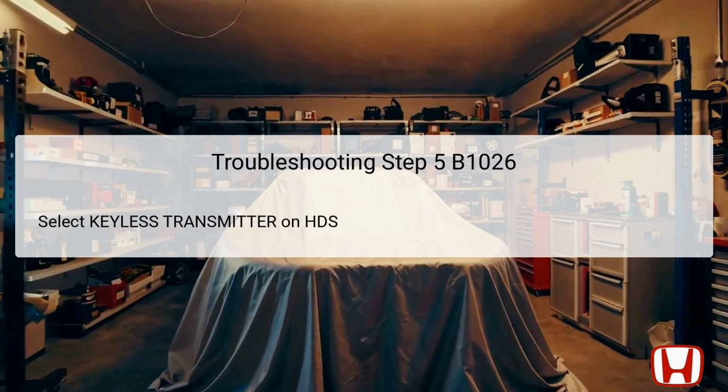In the fifth step, you must ensure that the front passenger's door lock switch is in the neutral position, and then select the keyless transmitter option from the HDS. The selection of this option allows the technician to access specific data related to the keyless entry system and its components. Ensuring the switch is in the neutral position is essential to guarantee an accurate reading.